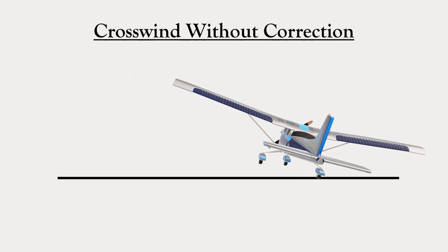Maybe you'll be able to lift off before you reach the edge of the runway. Maybe once the airplane's in the air, you'll be able to level the wings and get the aircraft under control before you hit something. On the other hand, maybe the right wheel will suddenly regain traction and you'll swerve to the left due to the left yaw. A competent pilot does not leave the outcome up to maybes.